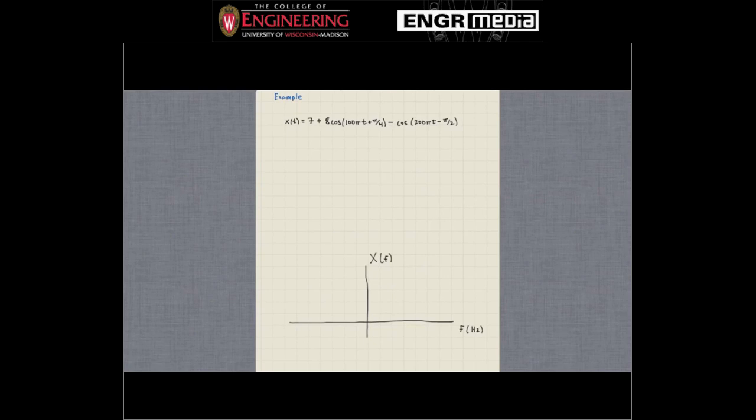Well, we have the signal x of t here. Now, it's written as the sum of three things. The first one is just the DC term, or the zero frequency sinusoid. So that's just 7. And that corresponds to, right, we've written A0 before. But that's just equal to A0. Right? So right away we could come down to this plot and say at frequency 0 there's going to be a sinusoid with amplitude 7. Right? All right, now the next term, let's just write this whole thing out.